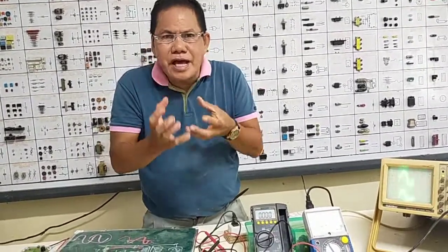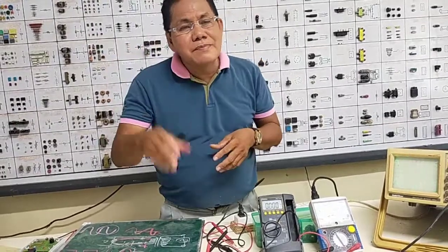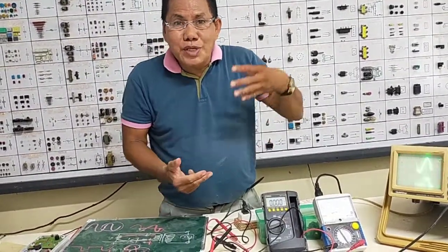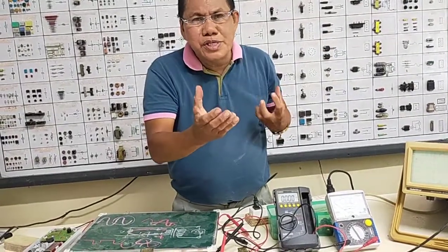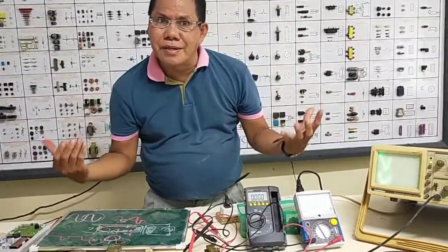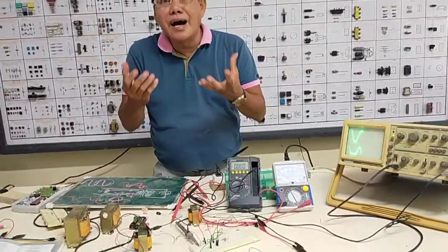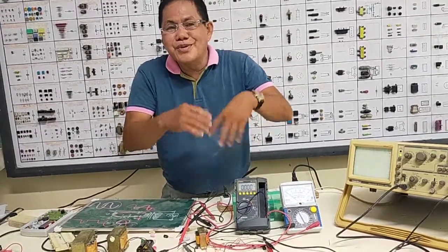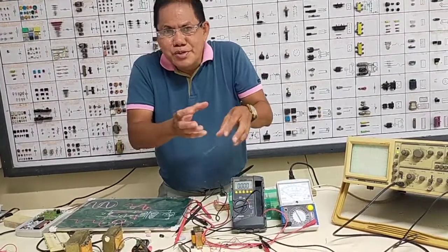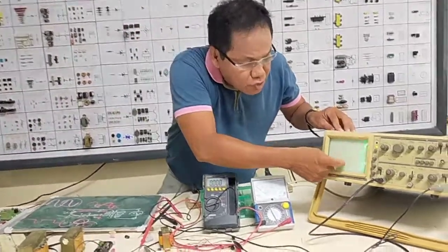In the sense that the audio frequency range, which are audible to the human ears, are ranging from 20 Hz to 20 kHz. Those are the audible audio frequencies. And 60 Hz is within this audio frequency range. That's why we can hear that one as hum. In your amplifier sound system, the music and the voices are accompanied with hum because of this variation.